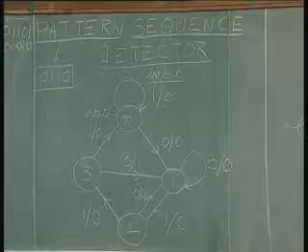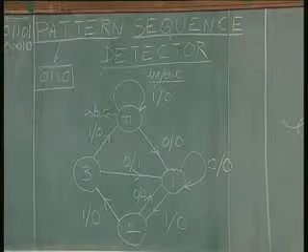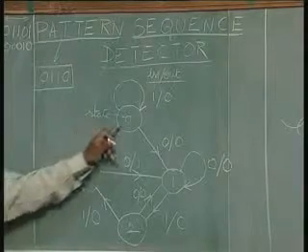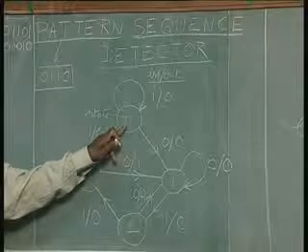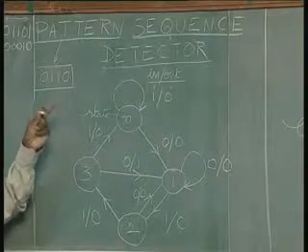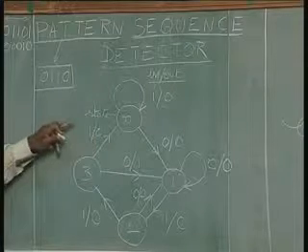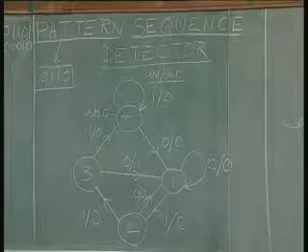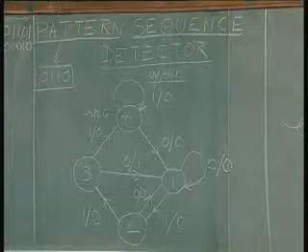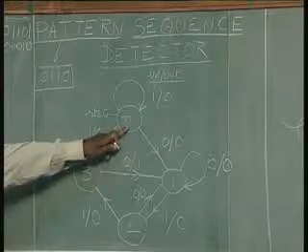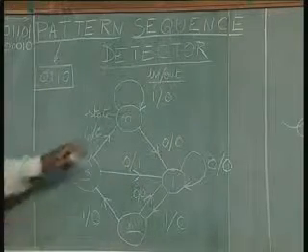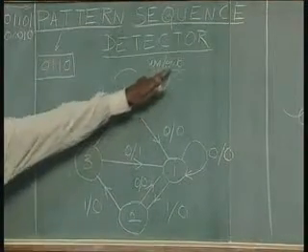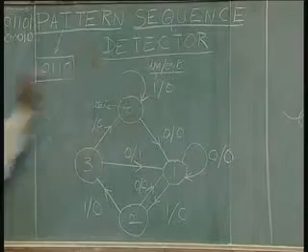Okay. So the only difference is, earlier you had used the notation S0, S1, and being a binary bit here, 2 bits here, right? So I am dispensing with binary and even the S0, S1 state notation, which we have seen in the earlier example of the sequential machine. And here we straight away put a decimal number 0, 1, 2, 3, and the arrows indicate the transitions. The first one is the input here, and the output is this. That's all you had to remember.